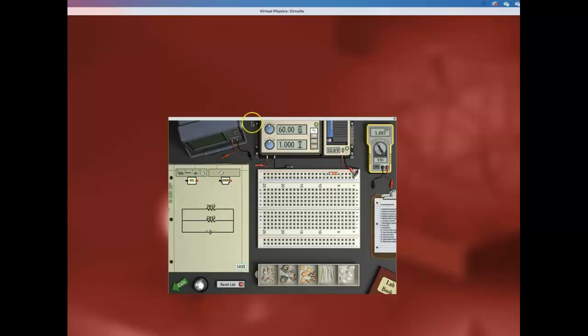Here, because of the parallel connection, I cannot have it still at 12 volts. This is gonna create a very high voltage because the resistance of the circuit will be decreasing. Then we're gonna make it 3 volts. Don't forget. Otherwise, the wires are gonna warm up and it's going to be very dangerous.